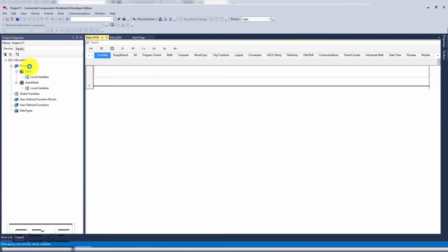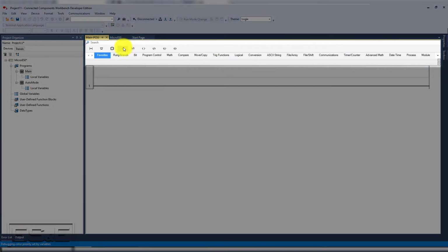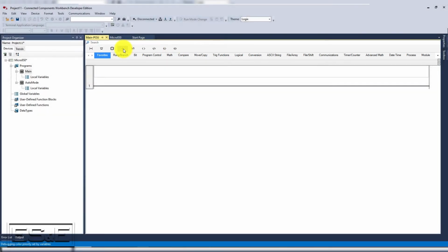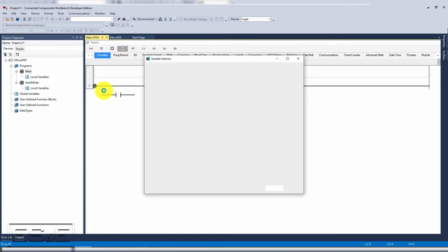You can now see the ladder editor, which has had some big improvements to resemble the Rockwell Logix software. There are the instruction folders along the top, and since we are in the Logix theme, the instructions look very much like any of the Logix software that you would have potentially used in the past. Let's build a very simple self-latching motor starter type circuit. We'll just grab an instruction from the top and drag it onto the rung.